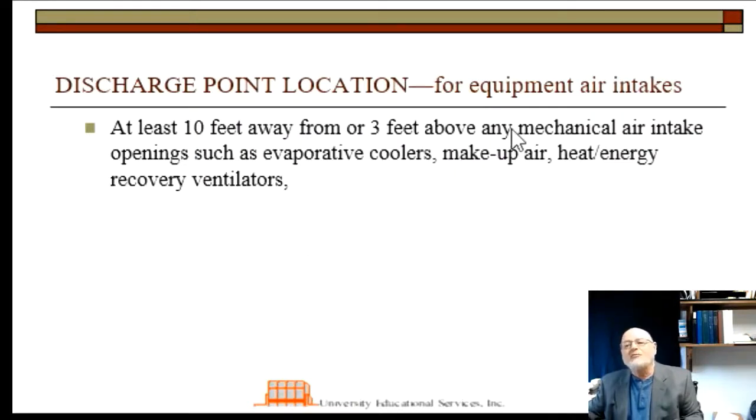Additionally, if you have equipment air intakes near where the exhaust point of the rough-in system will be, you need to keep it at least 10 feet away or 3 feet above any mechanical air intake. And some examples are given, and there are probably other examples available as well.